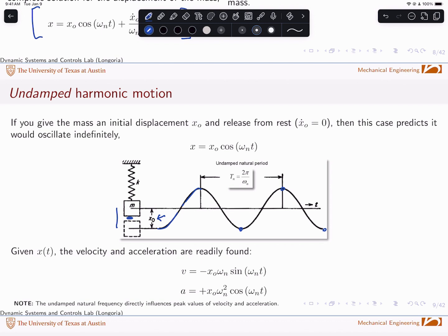You know that it's going to respond as a cosine if you release it from rest, so you take a couple of derivatives, and that means that the amplitude of the measured acceleration, that peak right there, all you have to do is measure that peak, and that's equal to the peak displacement of the system times the natural frequency squared. So if you can measure the period, and you can measure the peak acceleration, let's call that a naught, then from knowing the period, without actually measuring displacement, you can estimate it from that peak. Hope that makes some sense.